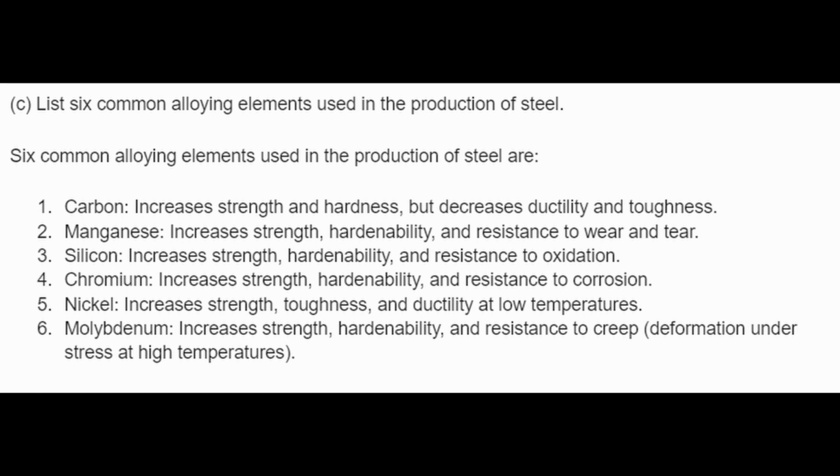Chromium increases strength, hardenability, and resistance to corrosion. Nickel increases strength, toughness, and ductility at low temperatures. Molybdenum increases strength, hardenability, and resistance to creep, which is deformation under stress at high temperatures.